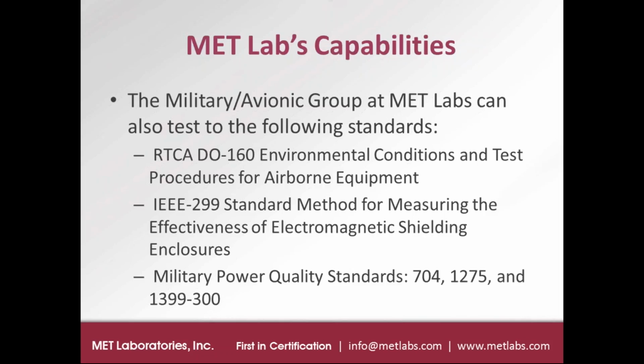We also do quite a bit of testing to military power quality standards, which is MIL Standard 704, 1275, and also 1399-300. Those are three standards, one for each platform: aircraft, ground vehicles, ships. I'm sorry, aircraft is 704, and then 1275 is ground vehicles, 1399-300 is ships.